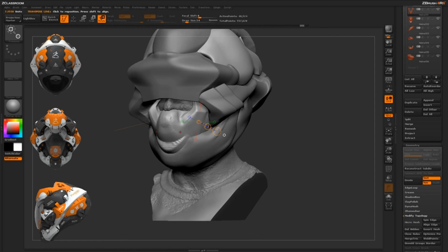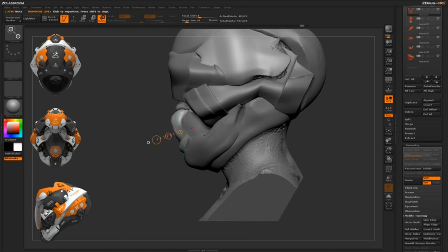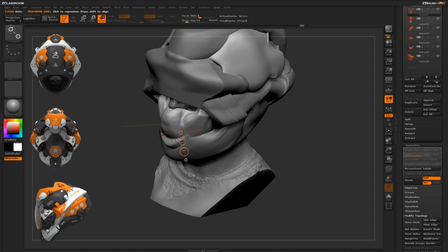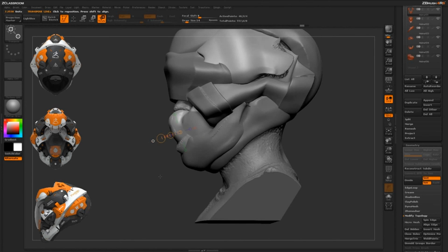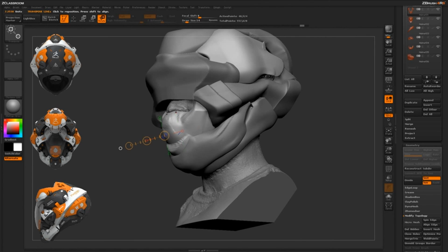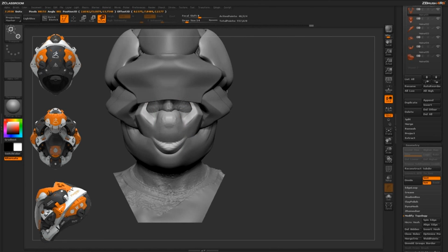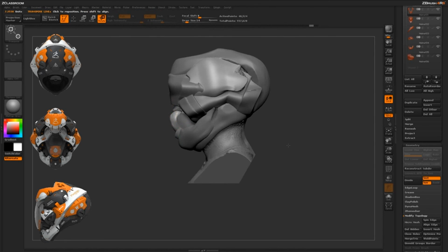So if for some reason I wanted to rotate 100% from this area here, I can click there, so it's going to give me that transpose line straight off. And then if I wanted to rotate it so it's actually going this way, you can come over and just select one of these angles that's going to give you a vertical alignment of that transpose line, and now I can hold that alt button, and now I'm getting a rotation right off that center point where I picked originally. That's another way to get joints and stuff established really quick, and then rotate and bend off specific points of your model.